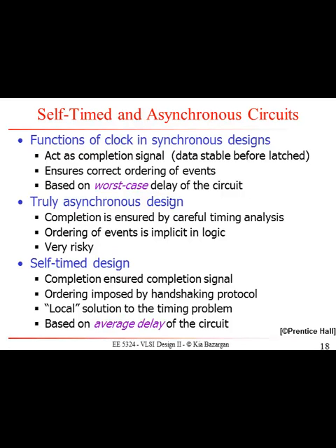Now, truly asynchronous design, I'm not going to talk about. People do use it in some memory applications in which you have a regular architecture and you could have a dummy row that transfers data from a memory cell to the bus. If you set that to be a representative of your worst case delay in your memory array, then you can rely on that to tell you when the read operation is done. But I'm not going to talk about that anymore.